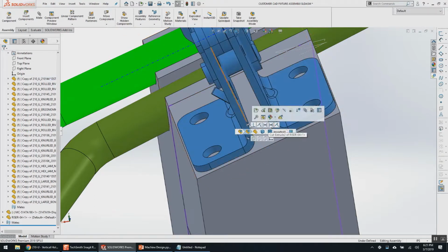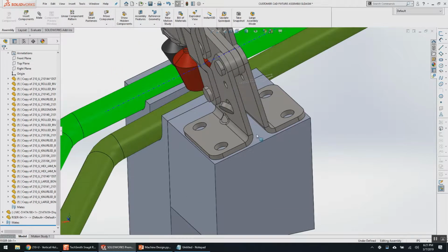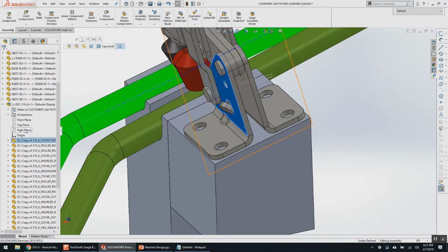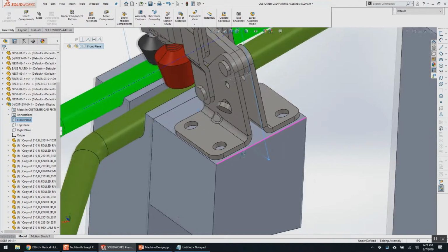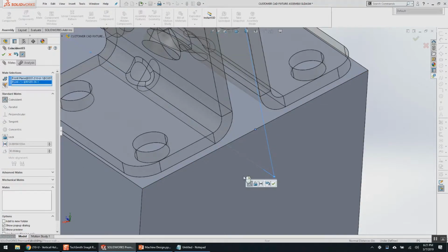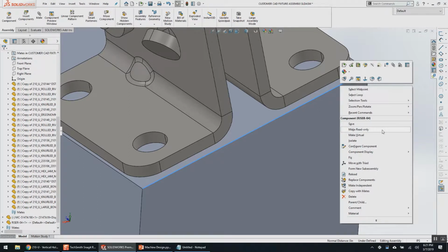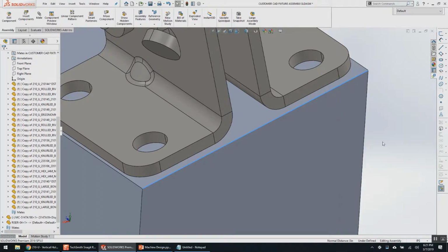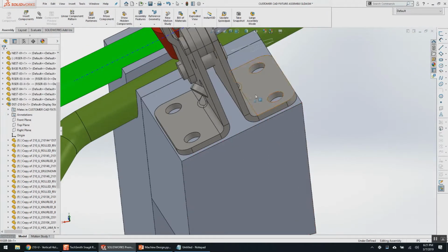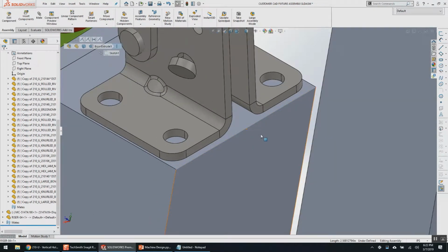Yes, that will work. I'm not going to say that's a bad idea, and I'll just do it here because it's a worthy suggestion to demonstrate. I generally don't like the midpoints, and especially for this where it doesn't matter enough to care. But Radar has a good suggestion, so we'll do the front plane there, do mate, hover, does it show up? There it is. Pick the midpoint. You can also right-click on any edge or line entity and select midpoint there. But that also works, that does get you in the middle.